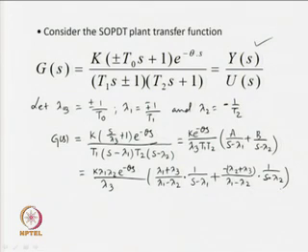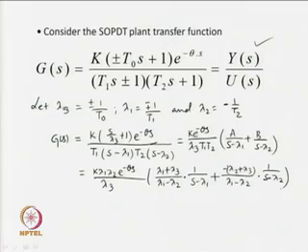So, why are we writing in this form? The benefit of writing in this specified form is that we will be able to get the transfer function model expressed in some convenient form. Now, we will be able to get the state space form of this transfer function model in diagonal form.